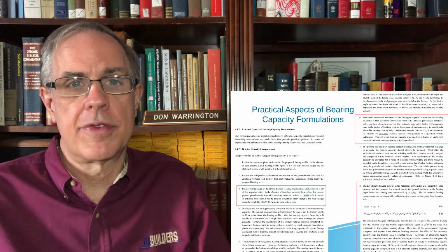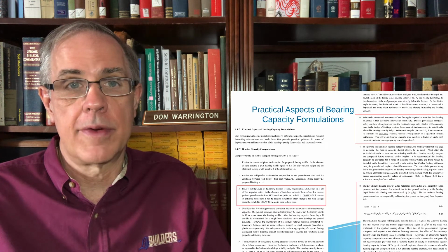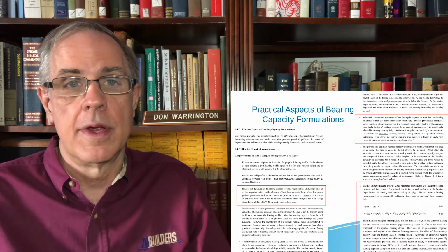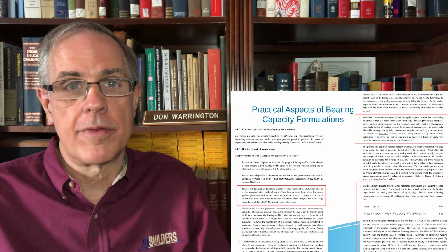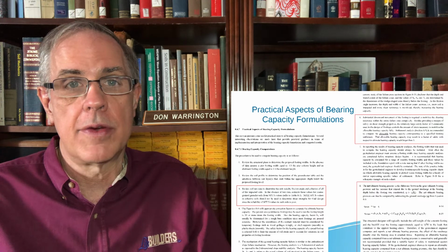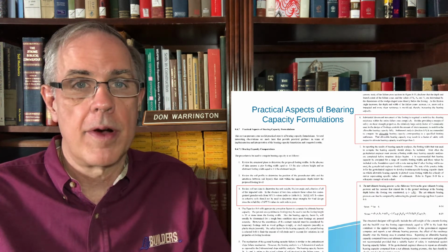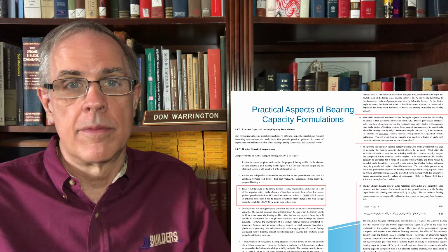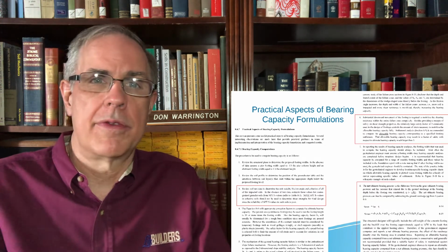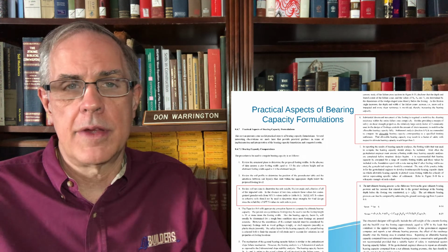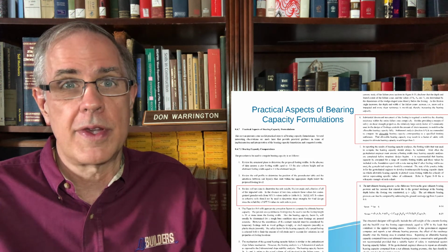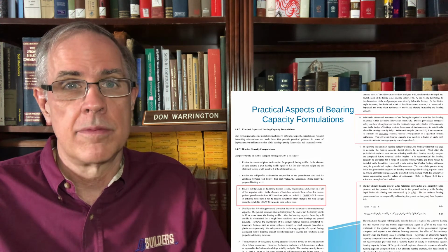It's possible that sites have severe non-uniformities, and around here severe non-uniformities are almost the rule rather than the exception. Then you need to deal with the fact that certain parts of the site will drive the design. So don't just say, well, we've got all this soil, we'll just run with it. In some stratigraphies you can get away with that, but in some you really should not do that.